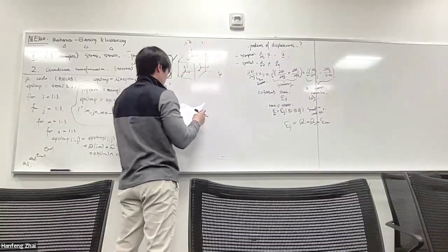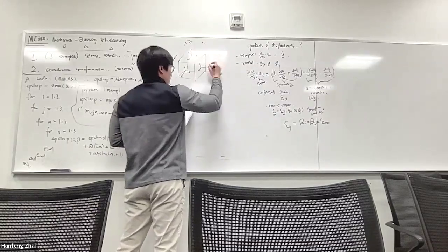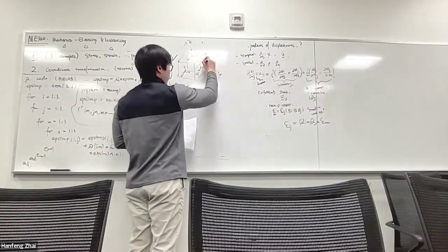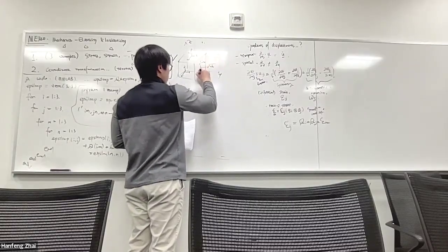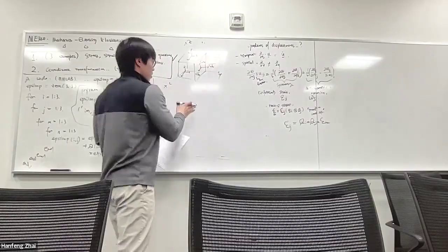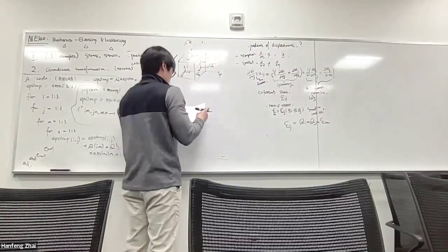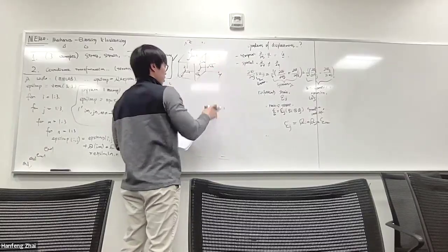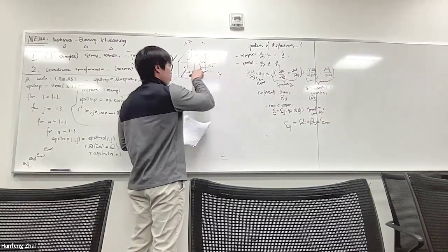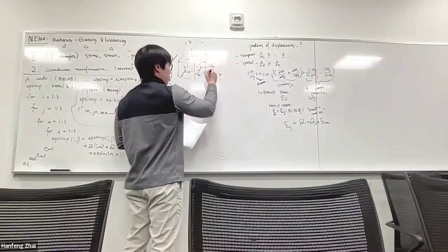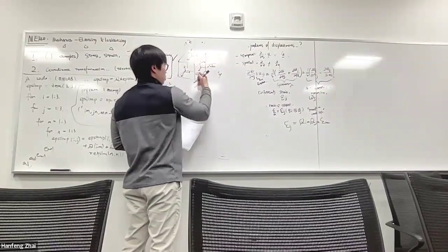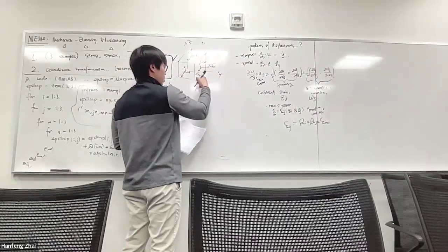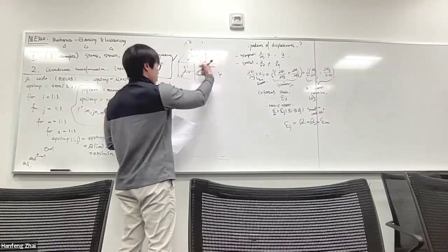So this is called a 2 surface or y surface. On this surface, all the stress components have first index 2 because it's on the y surface. And the second index of the stress tensor corresponds to the direction of the stress component. So for this component, it's pointing toward the y direction, so it's sigma 22. For this component, it's pointing towards the z direction, so 2,3, because 3 is z. And for this component it's 2,1, because it's pointing toward the x direction.